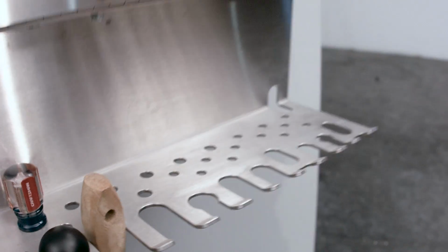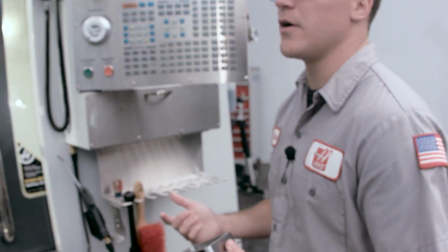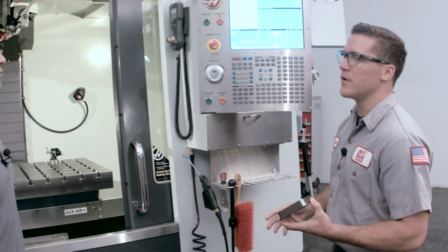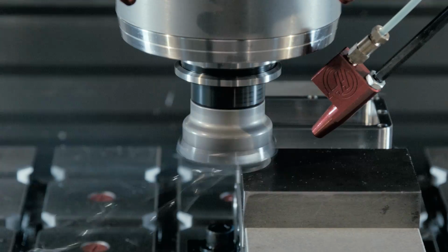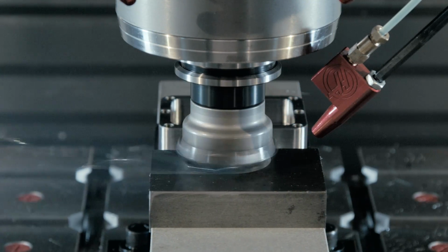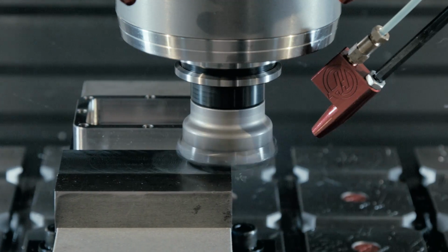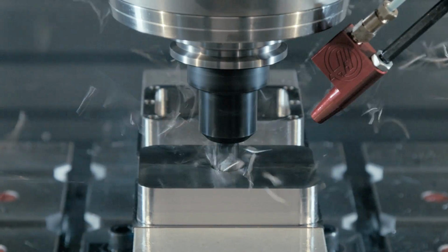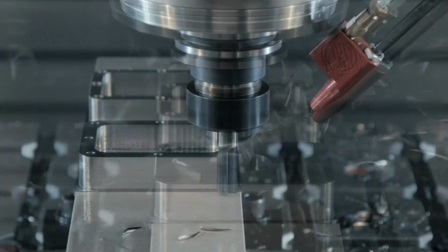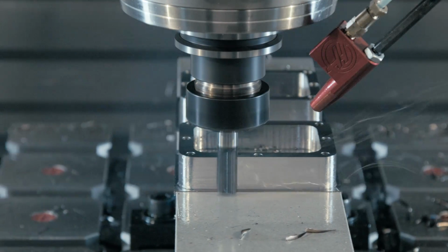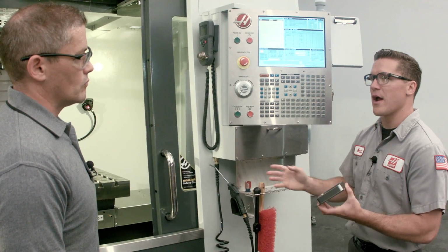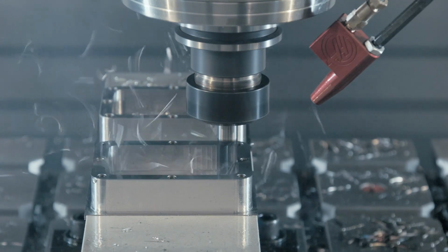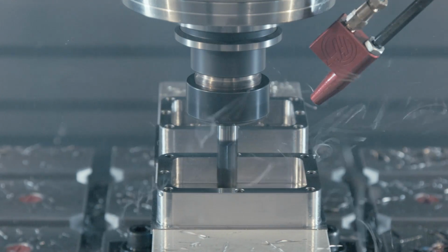So can you show us what you have going on this machine here? So we're cutting some steel on this VM3 here using a combination of high feed milling and MQL lubrication. I'm profiling the OD and the ID of this part using high performance carbide. The carbide, along with the aluminum titanium nitride, work well in this MQL application where we have higher cutting zone temperatures. And the high feed milling tool path strategy that we're using allows us to send the heat away from the cutting zone and into the chip.